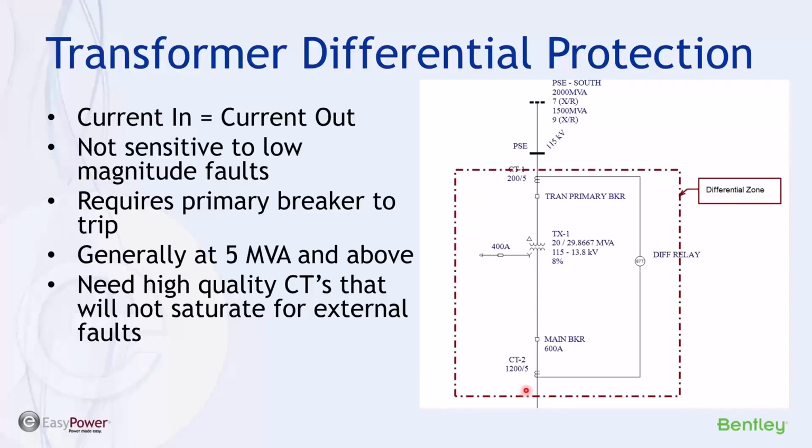So differential protection is considered the gold standard, but you need CTs on all three phases, both in and out. And again, you need to have a relatively costly medium voltage or high voltage breaker to be able to switch the input current.